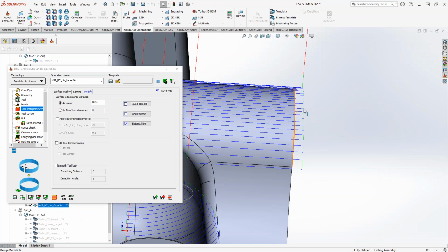And then if it goes a little wonky off the part, you're not concerned. Or if you just took out certain bits of the geometry and you get a clean toolpath, if it was just extended, then the same thing. You get the ability to just extend your surface kind of like you did here, and you don't even have to add new stock or new material. You can just basically say, just lead off by a little bit.